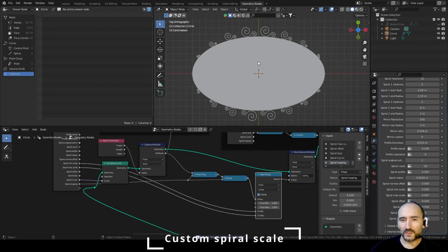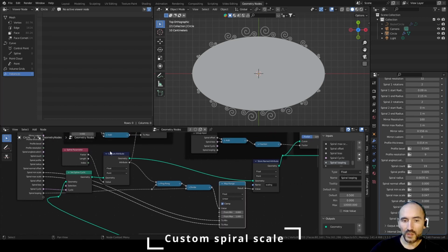Now because in the next part we will filter the visible of these instances depending on the scale, you can imagine that I want to shrink the min scale not from this point to the maximum point, but having a minimum range before it goes up to the maximum scale. You will better understand next with the filter, but now because we are here we need to add another attribute here, a float number that we can call spiral shrink value from 0 to 1 because with 0 I have no shrinking and 1 is the maximum shrinking, so the minimum scale needs to be from here to the maximum scale, so the total shape.